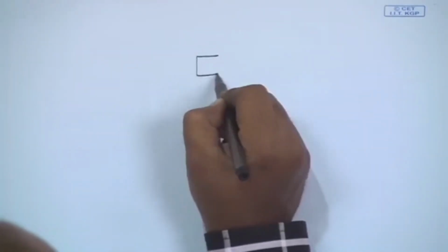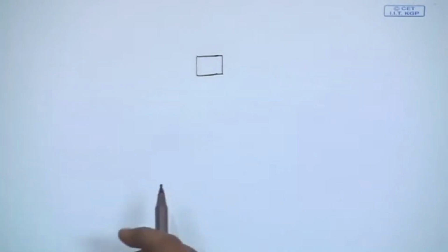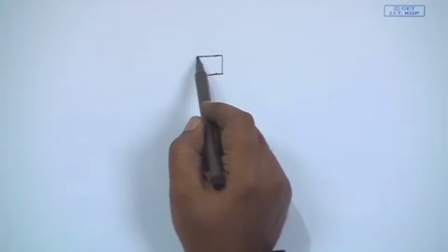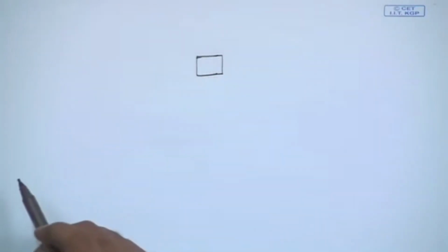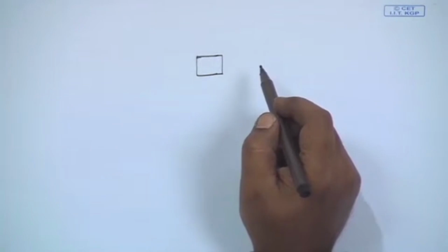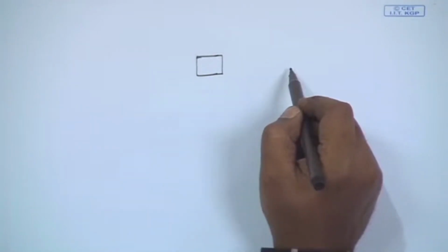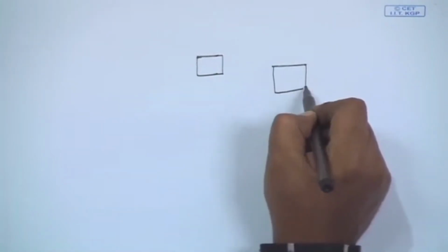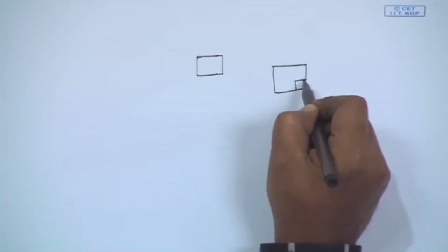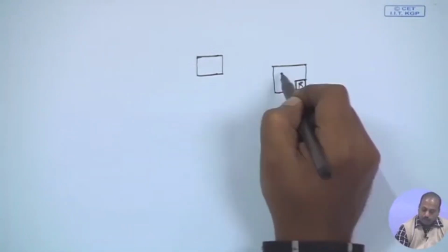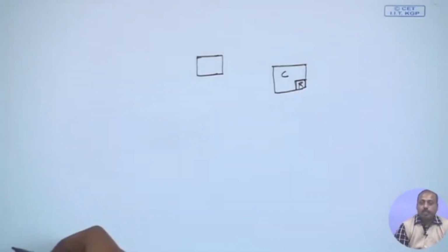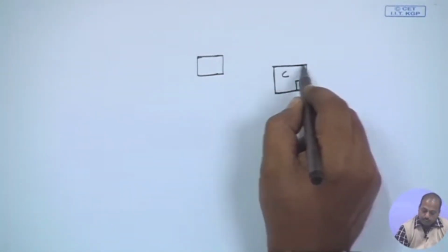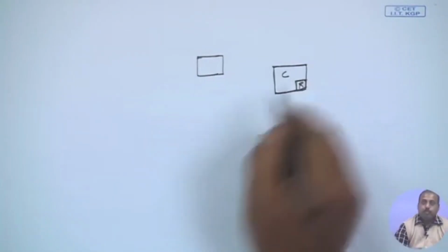The problem we have is in an SoC-based system, if a particular core is not active for some time, we can apply some power management technique to reduce the power consumption there. But in case of NoC, the router and core are often integrated. We make a tile, and at one corner of the tile we put the router. So this is the router and this is the core. That way the power management module comes for the entire tile, not for the simple router.